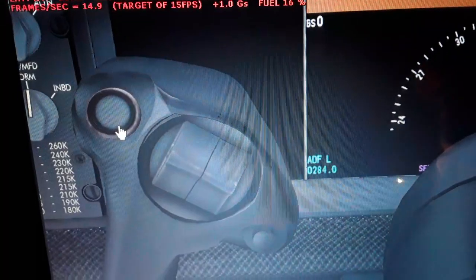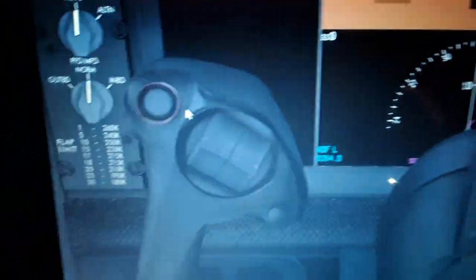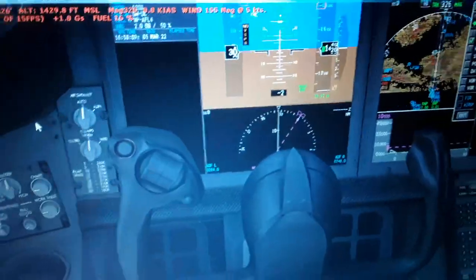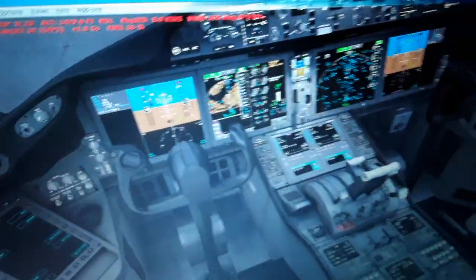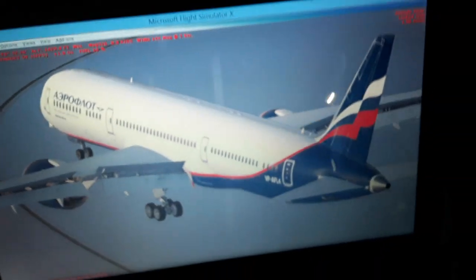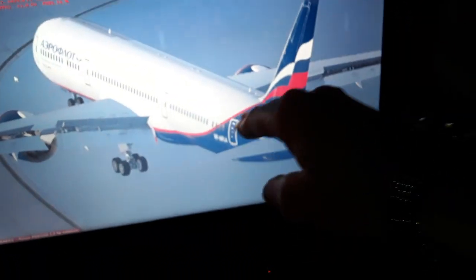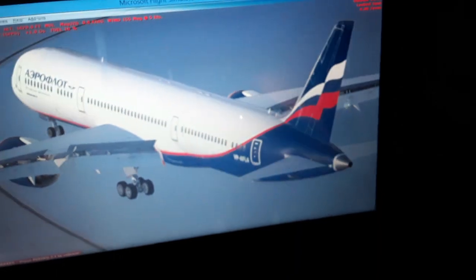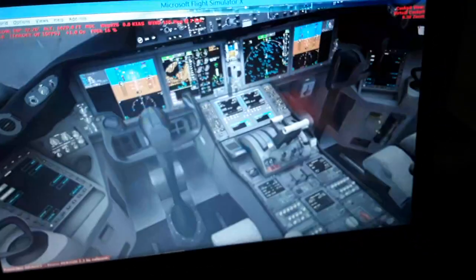And now the head-up display declutter. So you can see the airspeeds for the flaps also over here. Multifunction display switching. We can also see the horizontal tail elevator trim over here. You can trim the whole tail on some aircraft, or you can trim the elevator only.